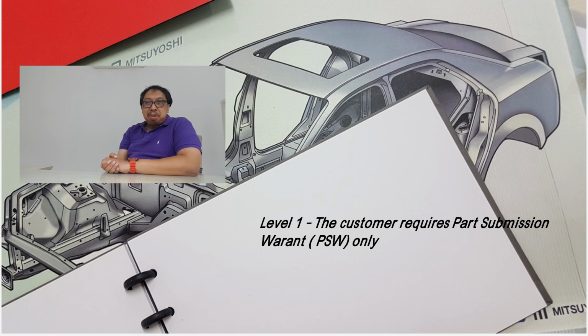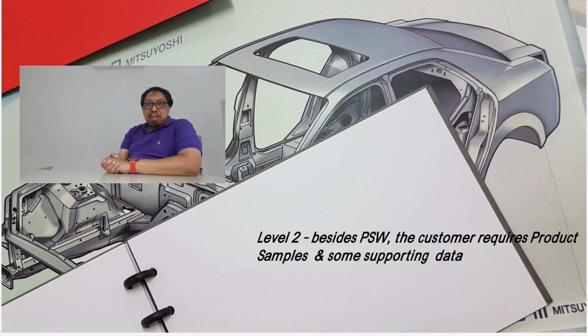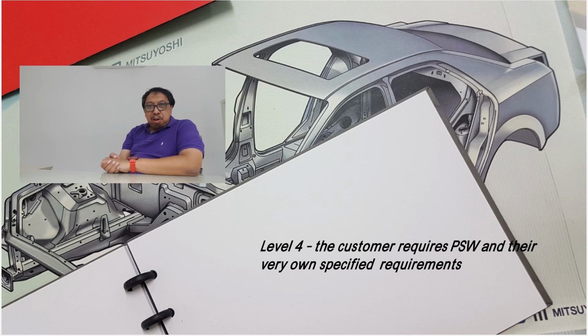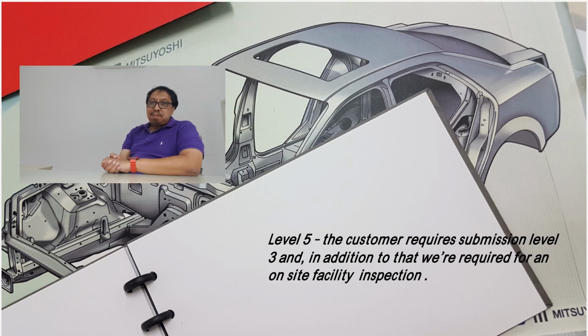Level 1. The customer requires part submission warrant or PSW only. Level 2. Besides PSW, the customer requires product samples and some supporting data. Level 3. Besides PSW, the customer requires product samples together with a complete set of supporting data. Level 4. The customer requires PSW and their very own specified requirements. Level 5. The customer requires submission level 3, and in addition to that, we are required for an on-site facility inspection.